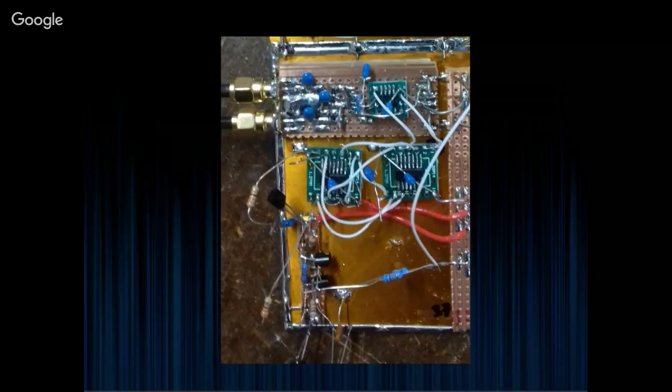Where you see all these little black transistors is the charge pump, and it got hacked around because I tried a few different things. What you see in most of the literature is they optimistically show a switch. I think this is just to be intuitive, and they say, if you trigger one of the flip-flops, then flow current through here, and if you enable the other one, discharge current out of it. The actual implementation is not that simple.